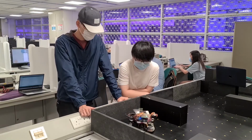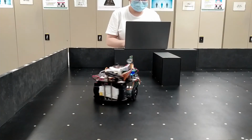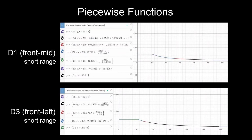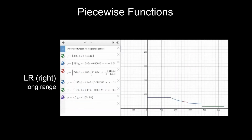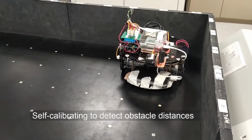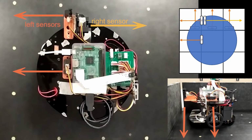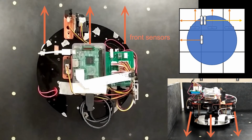We implemented PID closed-loop control for our motor. We even had to tune PID frequently to make sure our robot can move in a straight path. Piecewise functions were also added to improve accuracy of the sensors. They were able to detect obstacles pretty accurately. We accounted for fluctuations in sensor readings. We finalized the overall structure of our robot to suit the algorithms' needs.